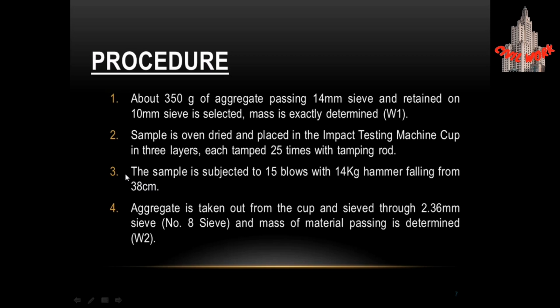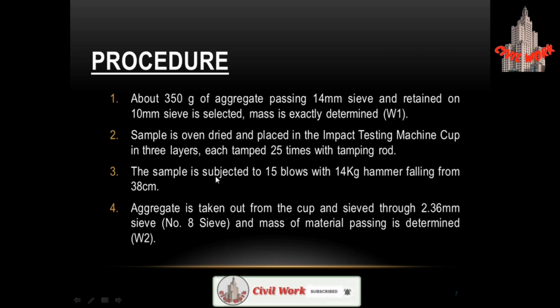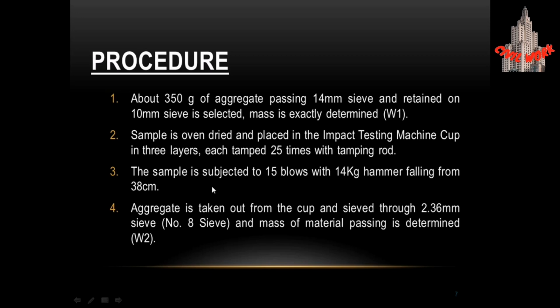Point number 3 is that the sample is subjected to 15 blows with a 14 kg hammer falling from 38 centimeter. It is clear from it that when we have taken our sample, then we have to apply 15 blows with the 14 kg hammer, which has to fall freely from 38 centimeter.